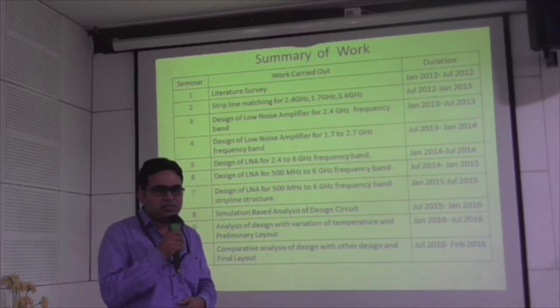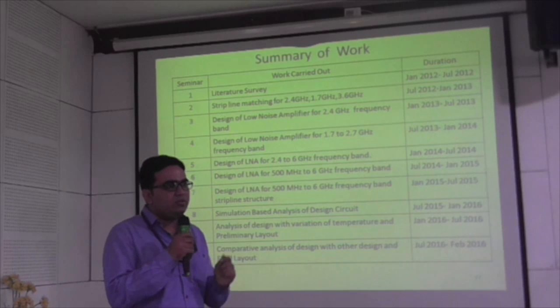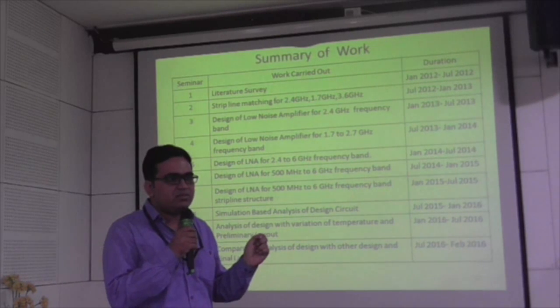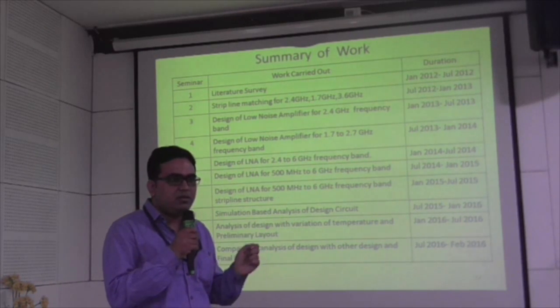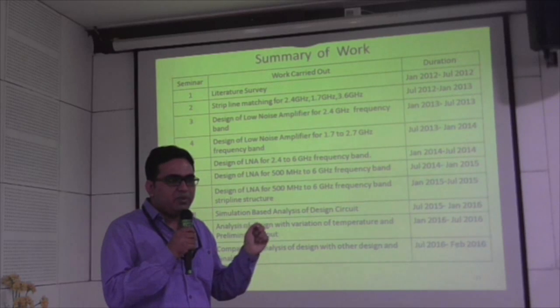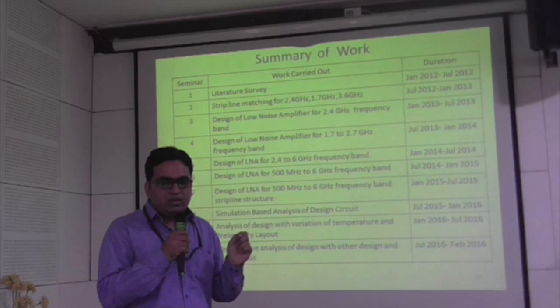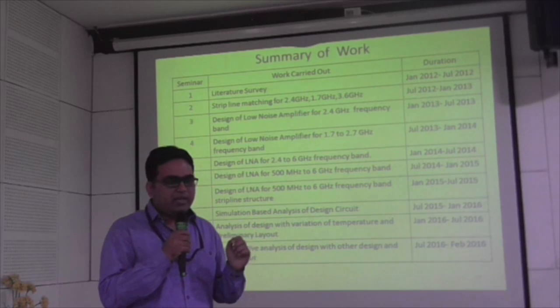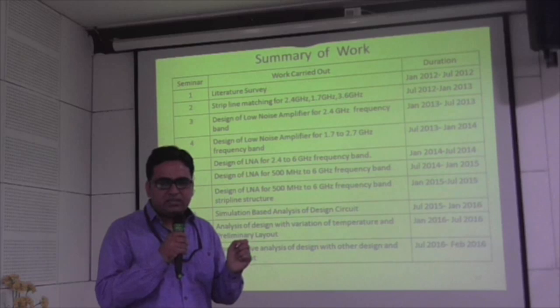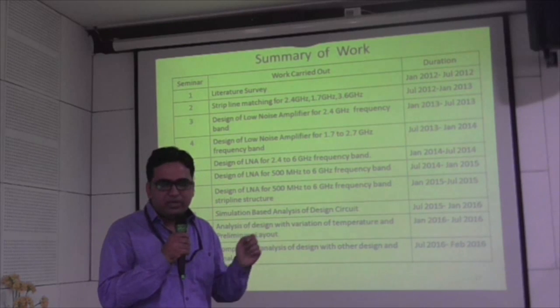First is the literature survey. Then I worked on the matching structure, because the matching structure is very important to minimize the noise figure and to maximize the gain. So I worked on the strip line structure. Then I designed one LNA with the basic self-biasing structure at 2.4 gigahertz.